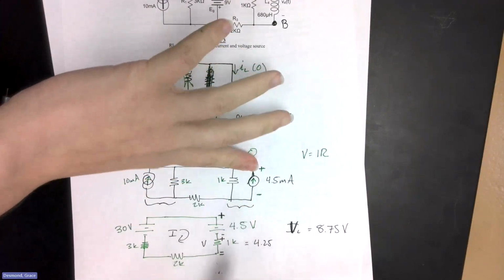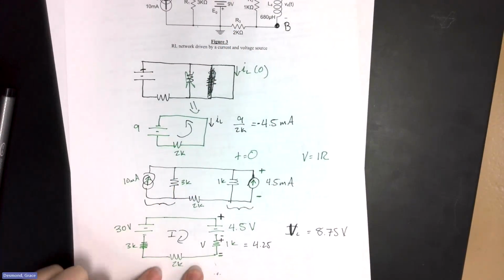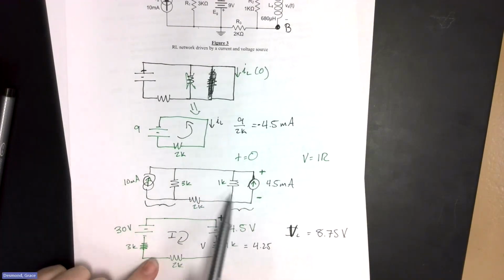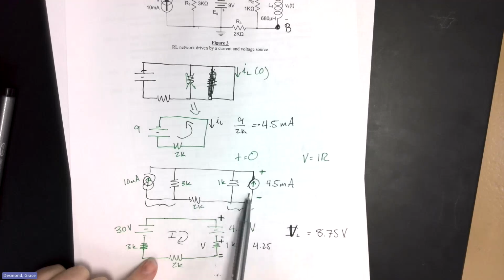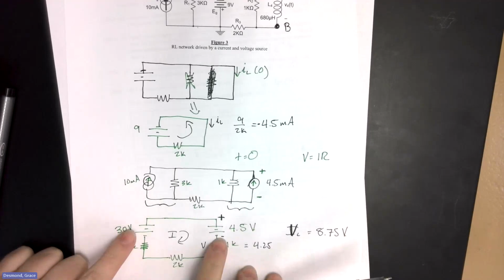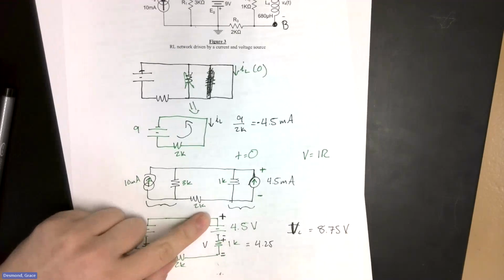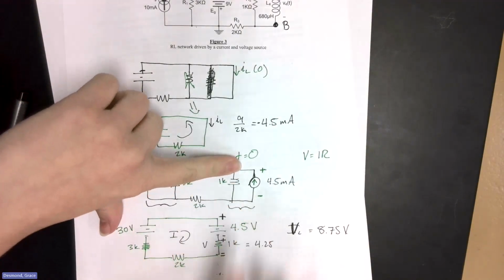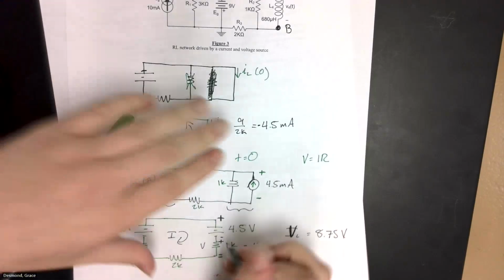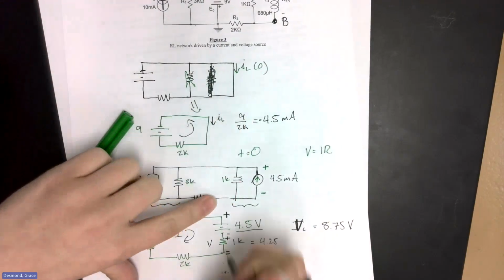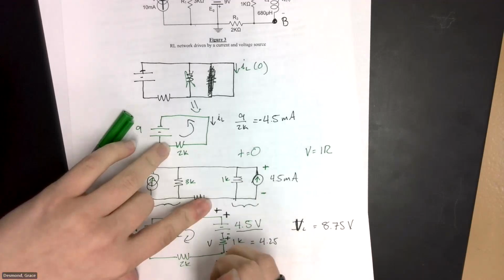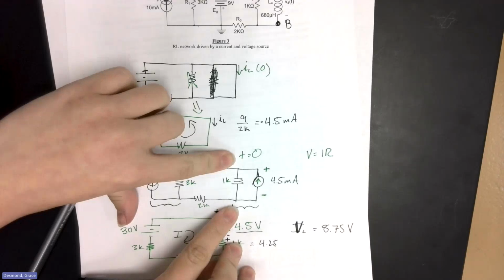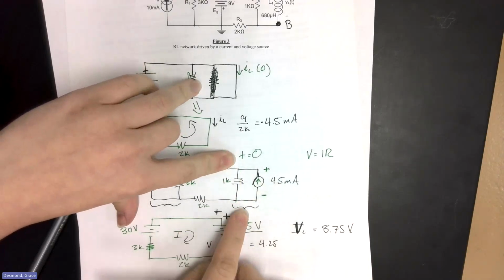What we did is we said it would be really easy to find current and voltage if this was just one loop. And we realized that we could combine these two and combine these two to get 2 voltages. From there, we realized we need it from this node to this node. So it's not just this voltage. It's not just this voltage. It needs to be the voltage from up here to down here, because that is what this means. It is the equivalent from both of these.